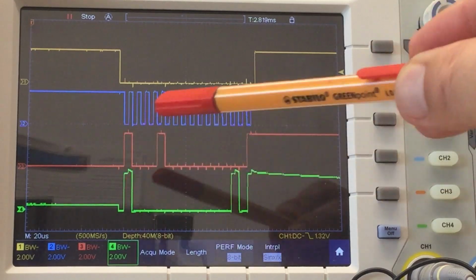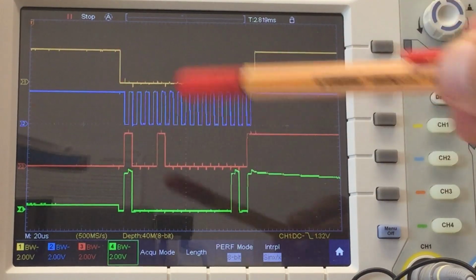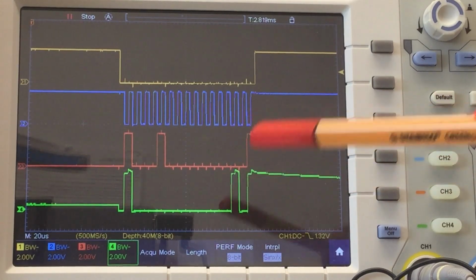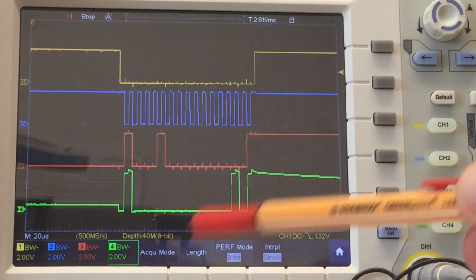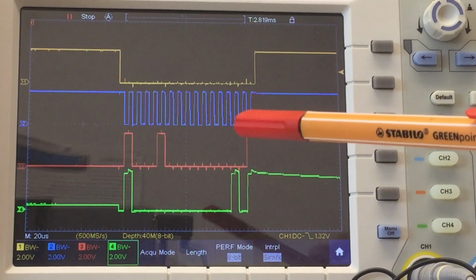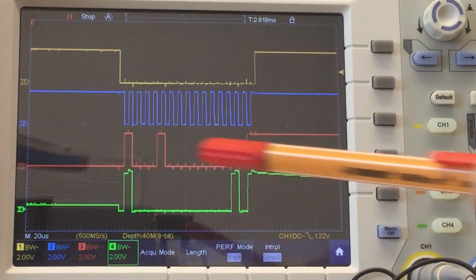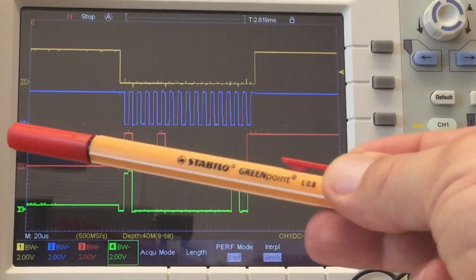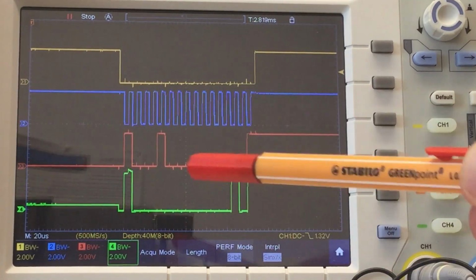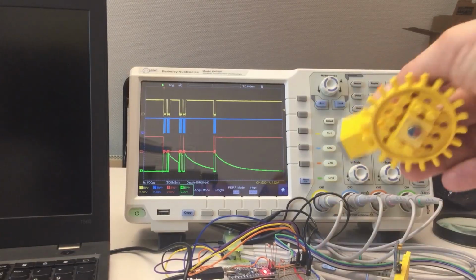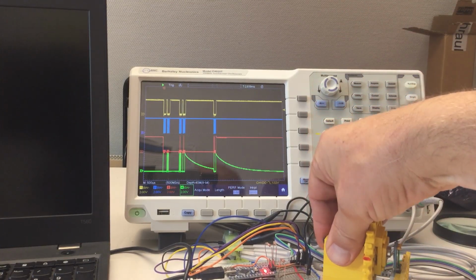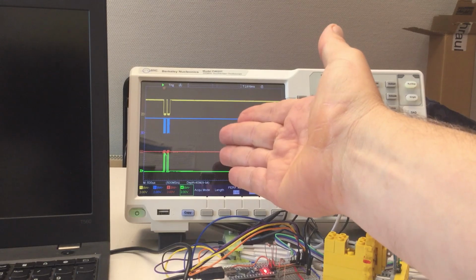Obviously, 2 bits here to address the register, and I think the last bit here, if that is set, that means reset the error registers. And what's returned here is still the error register, because that was the last command we sent. And if I return the magnet to its rightful place again, everything gets back to normal.